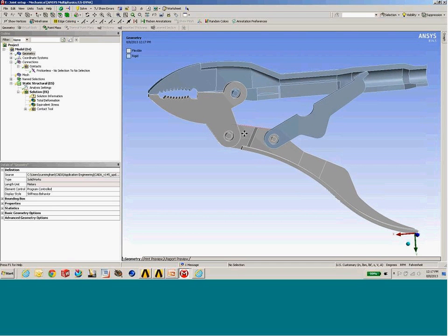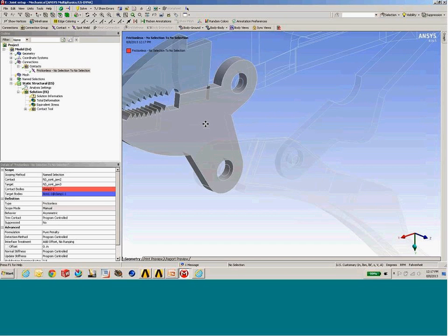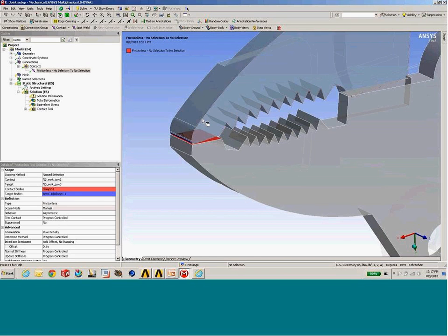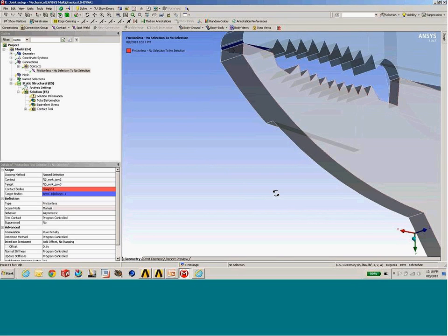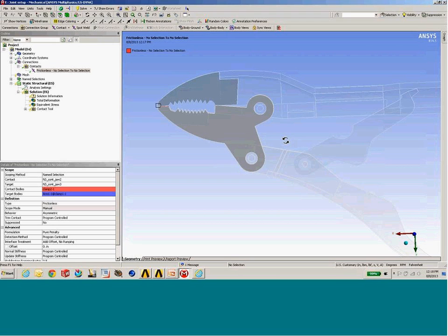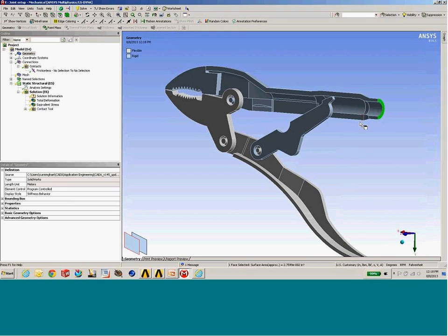We can do things like use a surface-to-surface contact region between that flexible body and also the rigid body. The rigid body in this case would be the target surface for that contact region. So that's possible between flexible and rigid bodies to do the nonlinear contact. As far as the joint connectors are concerned, we can put them in manually. So let's start out, say, on the end here with the very end of the wrench. Let's say we're going to fix it at that end.